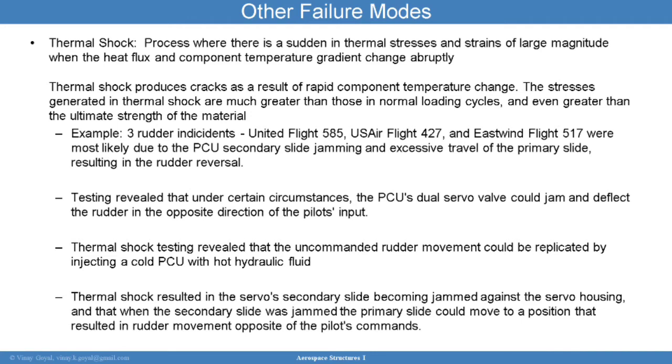Later on, the teams of investigators conducted thermal shock testing, which revealed that the uncommanded rudder movement could be replicated by injecting a cold PCU with hot hydraulic fluid. And so this is a type of thermal shock test, and that resulted in demonstrating that the servo secondary slide became jammed against the servo housing.